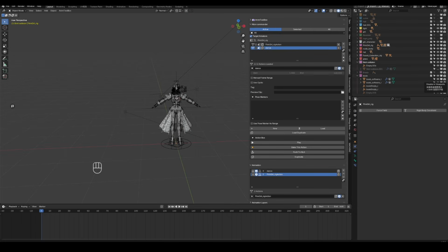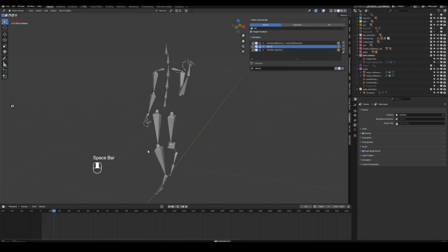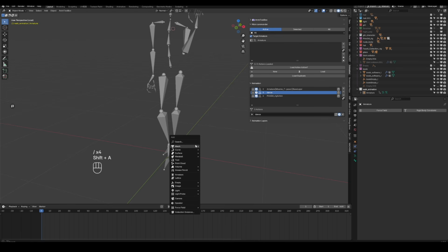Next, let's bring the animation into Blender. I'll just drag the file in. When you import it, make sure to enable the armature option for automatic bone orientation. Then click Import. Once it's in, we want to transfer this walk animation onto our own character.